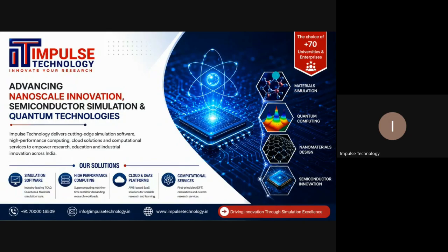In today's class, we go through the atomistic package, like finding the band diagram for silicon and germanium, and finding the eigenstate, eigenenergy, and valley splitting through the atomistic package. Apart from that, we also go through the fully depleted silicon-on-insulator for a single quantum dot array and create a geometry file through the QTCAD builder option, through Python code.